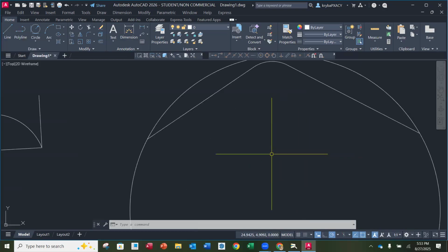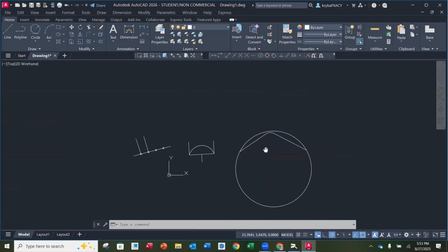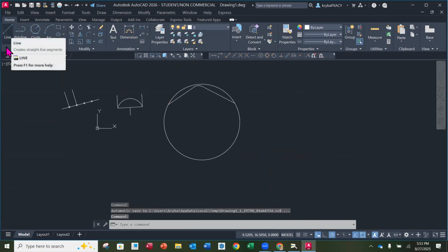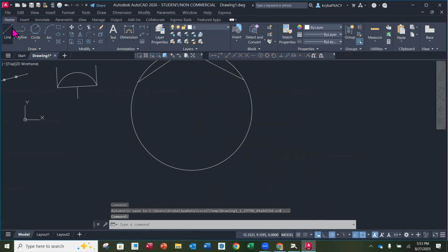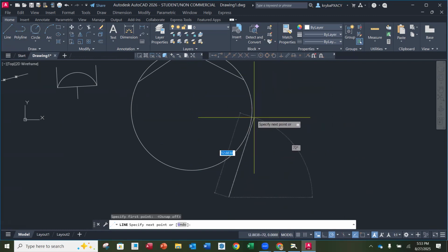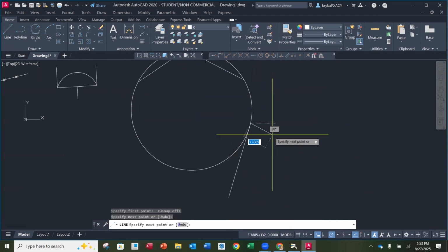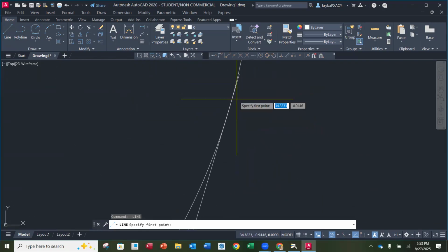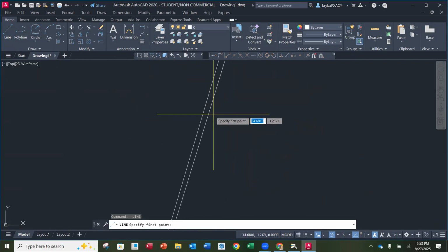Another one, which I think we've exercised as well: a lot of times we want lines to be tangent to circles. Never, never, never just put a line in place. Now, I don't have tangent on here. Oh, it's hovering to the center. So again, annoying, I'm just going to turn it off for a second. If you go close to an edge here and create this line, it looks like it's nice and tangent. But if I zoom in, it's over the top, and it's really not tangent.